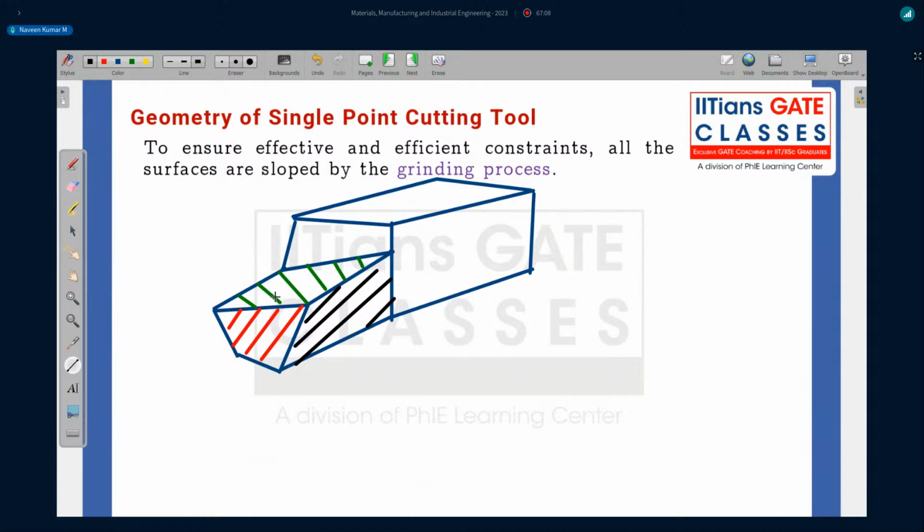Okay, all these angles are visible, and this will make your cutting edges efficient. So this will clear your workpiece from rubbing, and this angle on that will make sure that your chip is flowing away from the machining zone. All these things are happening here.